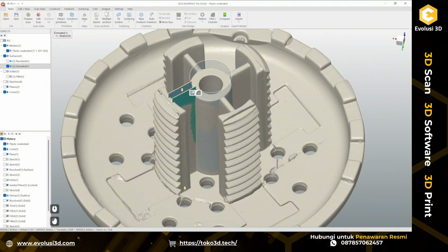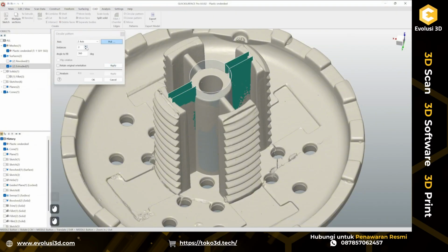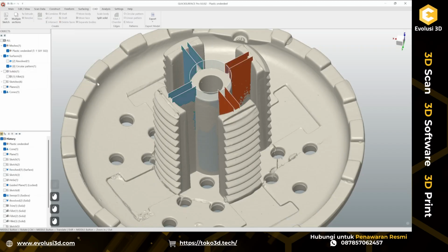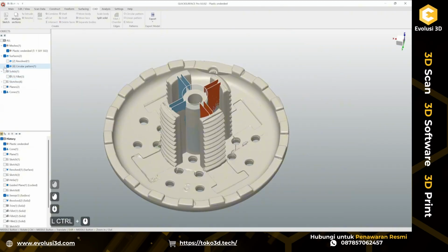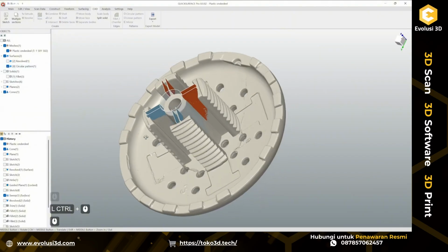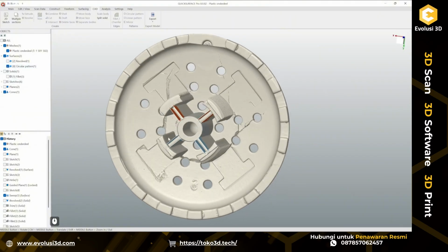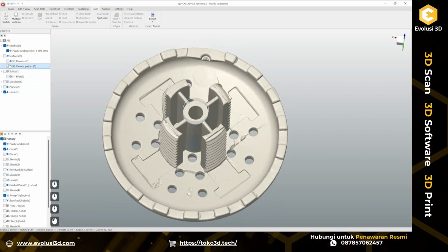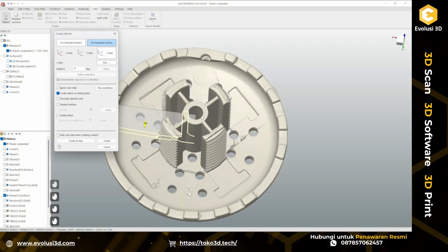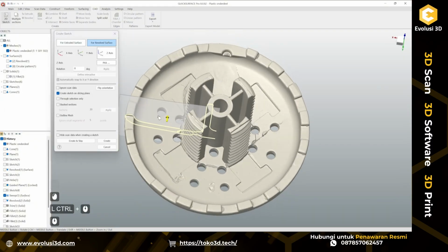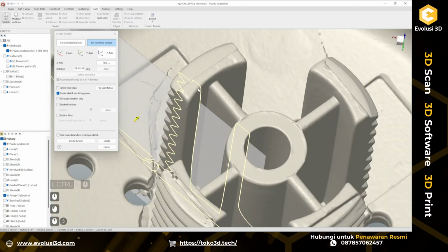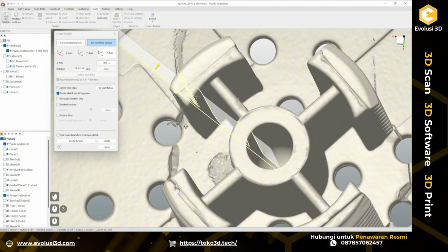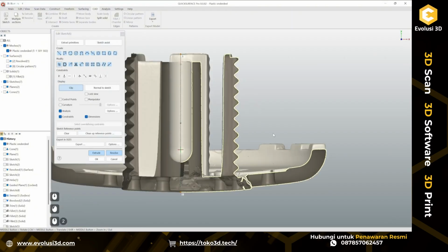So for now, I'm just going to do a circular pattern of these last extruded surfaces like this. And what I need now is another cylinder or cone. In order to do that, I'm going to create another cross section for revolve. Move it slightly, something like this.